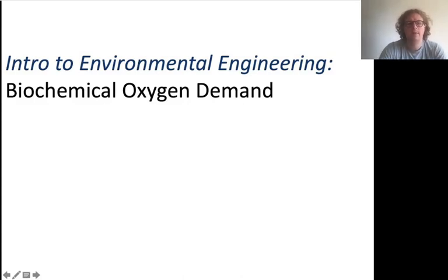I want to talk with you today about BOD, or biochemical oxygen demand. And so this is all about how the organic matter in the water is going to be degraded and in doing so consume dissolved oxygen out of the water column.